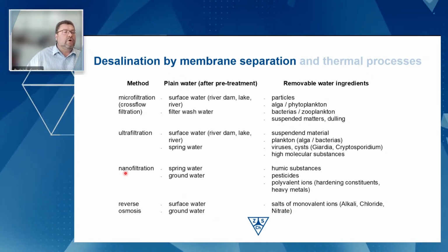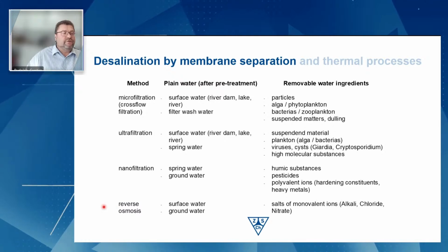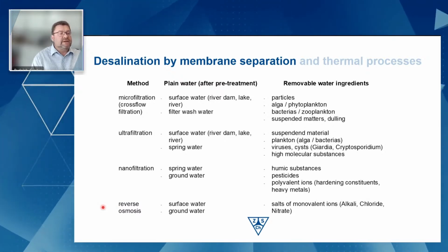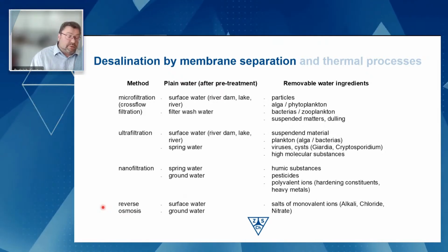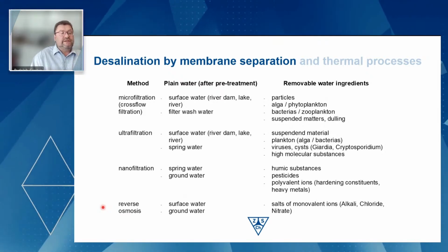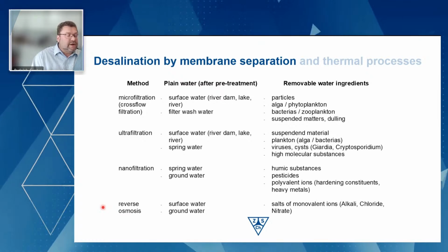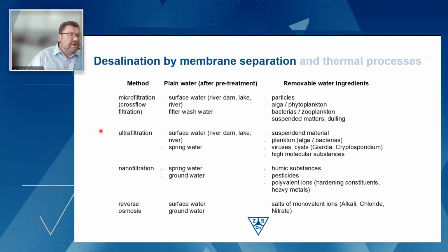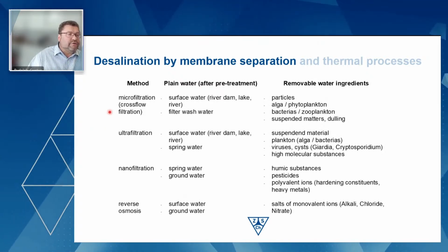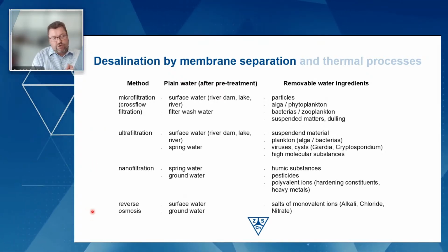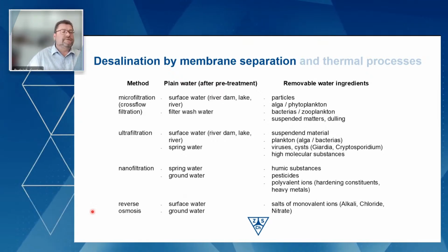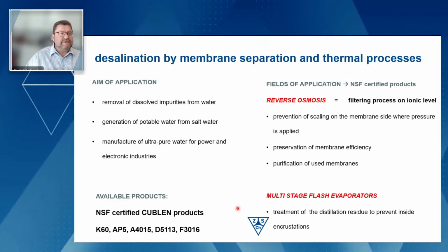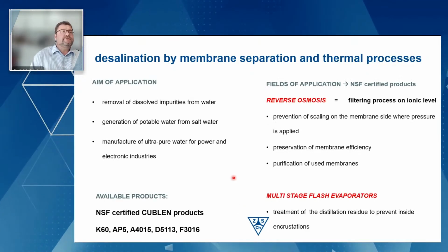And depending on the steps, different technologies are applied to keep the system running, and sometimes or even quite often, these techniques are combined. So, for example, in front of a reverse osmosis, ultrafiltration or microfiltration is applied in order to make a pre-treatment of the feed water. So this depends on the technology which is used.